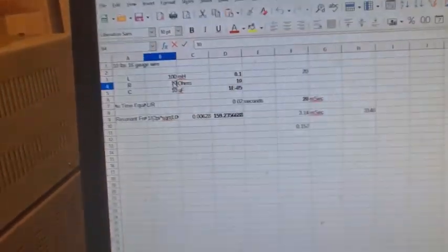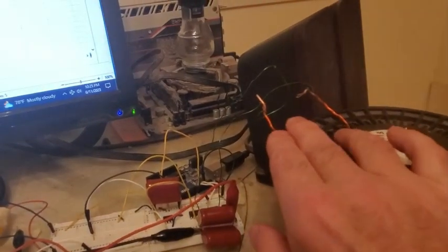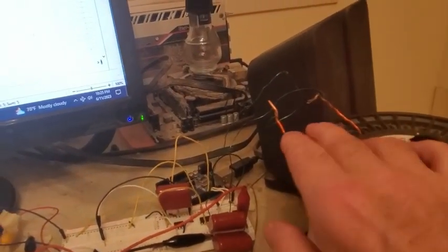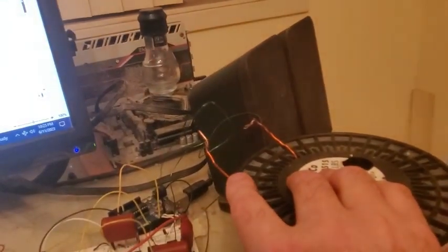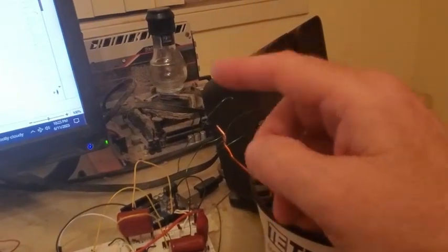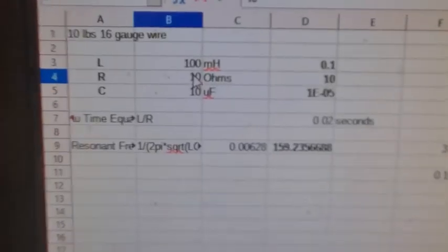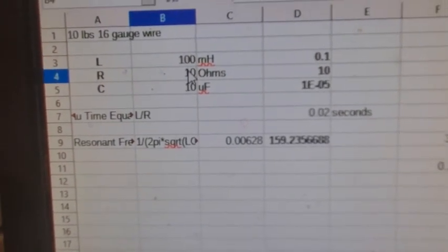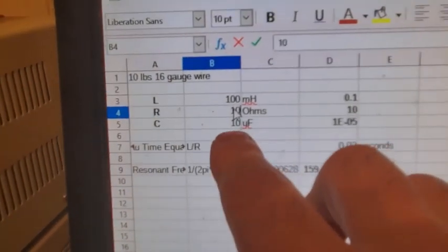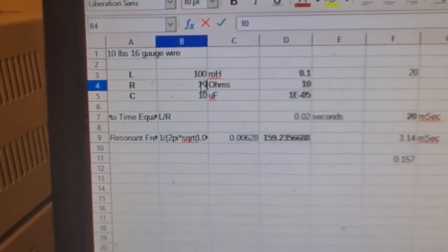And that's your sharp transient. As you start getting thicker and thicker wire, skin effect begins to play a much bigger role. We could go to a skin effect calculator, but I'd say somewhere around 120 UF. If you were oscillating AC, that would be a big problem with this 14 gauge. And so you want thinner wire. But if you use thinner wire, you have more resistance. But you need to cut down the resistance, so you go with thicker wire. But then you can't go with as small a cap for as fast a pulse as you want. So what do you do then?